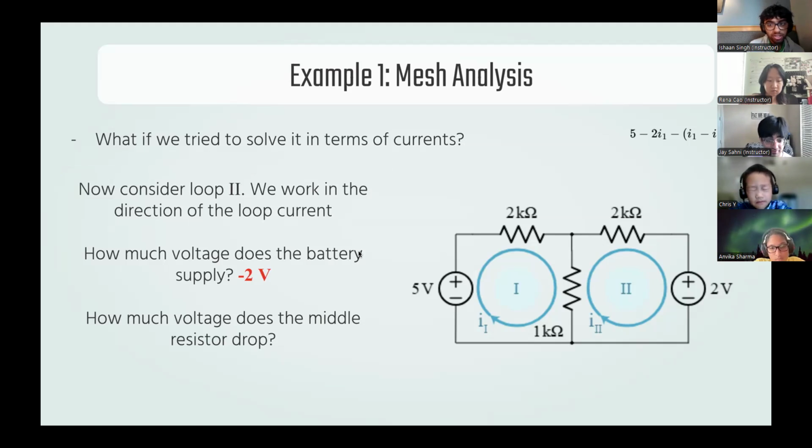And since our current is going into the battery here, we need to take that into account, because when we construct our overall KVL expression, we need to make sure that we account for that opposite direction of the loop. We could have equivalently drawn this loop going counterclockwise instead of clockwise, and then all the signs in the math that we've already done and that we will do would be swapped, and it'll work out the same. So it is a choice, and as you'll see in the next example, example 3, that choice can be made to be convenient for you.